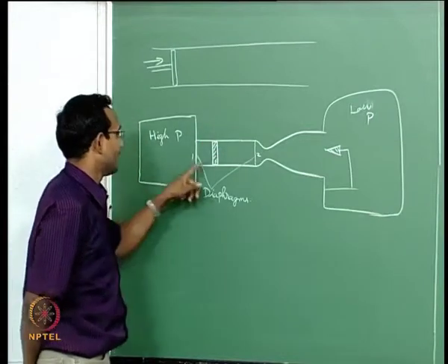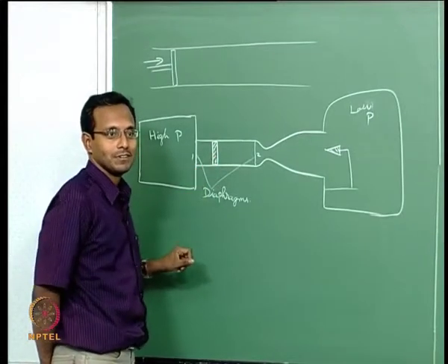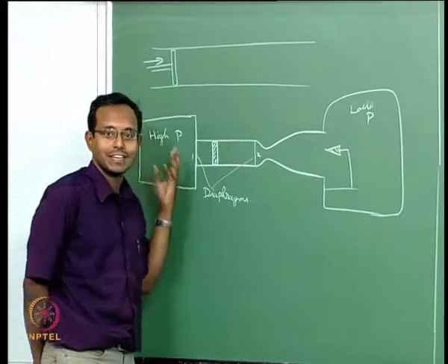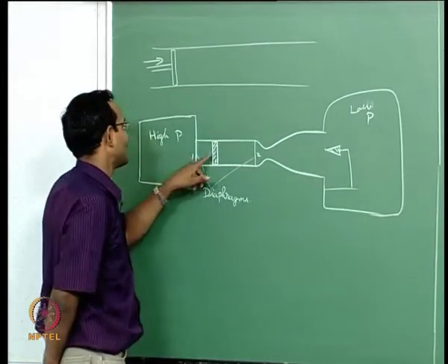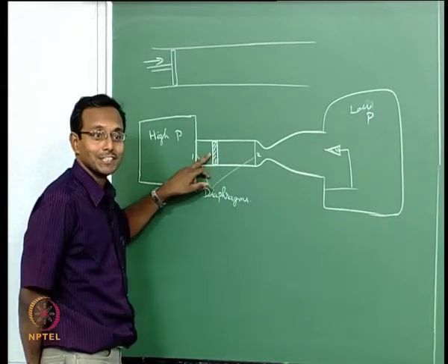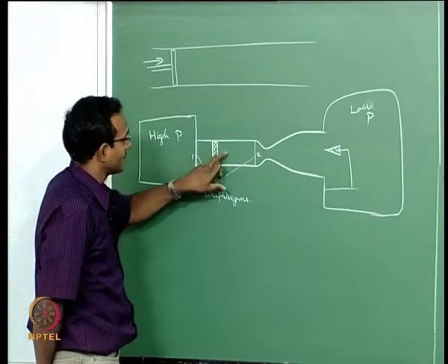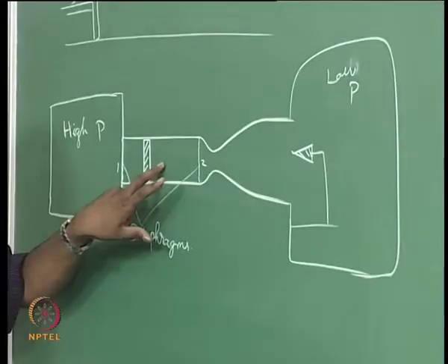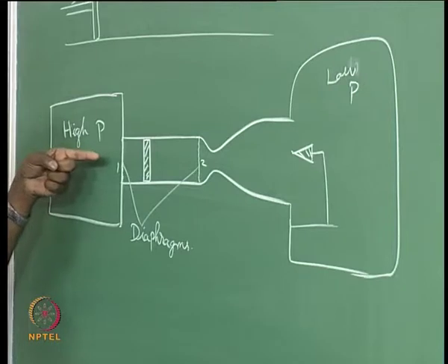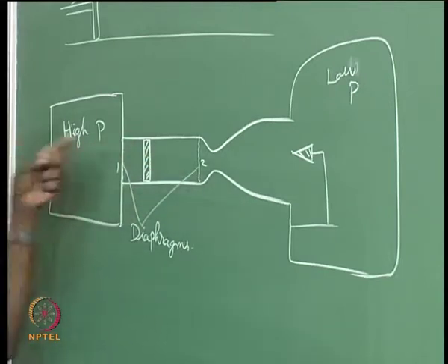now I am going to say the end wall is not actually a fixed wall, but it is a piston. The shock will bounce on it and come back, like any other shock. Immediately after it bounces back, what is going to happen? The pressure behind the reflected shock is so high on one side of the piston, while the other side is still the same original low pressure. What is going to happen because of that? The piston experiences a net force this way, the delta P times the area of the piston, that much force is being experienced,